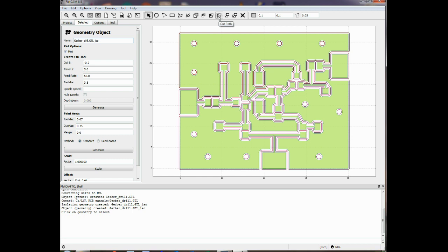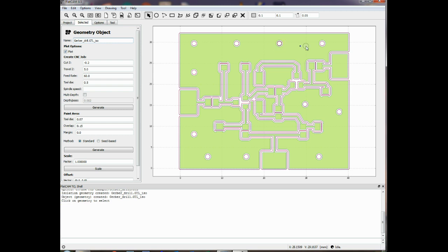And there's a button up here, so we'll cut path. So I've highlighted this hole, and it's highlighted a whole bunch of other stuff. So hit cut path. It does exactly what it says on the tin. Cuts the path. Now if I click on the hole, only the hole lights up. So now all these other holes on the top here are also part of the same path, so they've all been disconnected as well. So just quickly check.